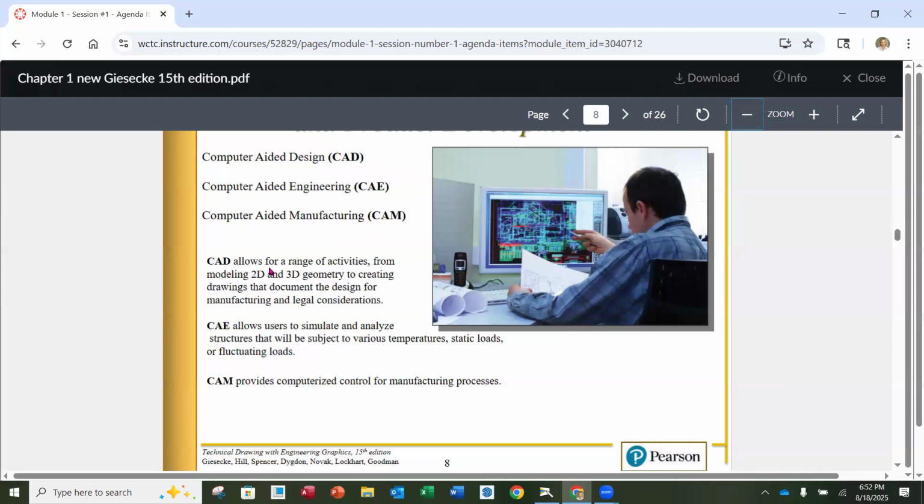Now, it starts with a CAD model. So as a designer, as an engineer, if you are creating that initial CAD model, it is so important that you have good geometry and integrity in that file. If you don't, things like corners not meeting or overlapping, CAM software can't handle that. It gets really confused and it's like, can't do it. So it's really important. And that's one of the things that we teach here at WCTC: we teach you the good practices, the good construction.